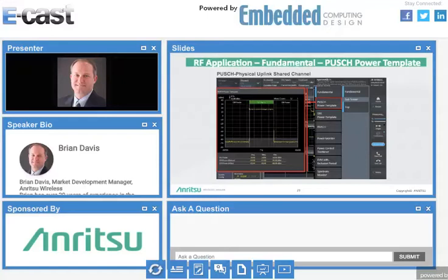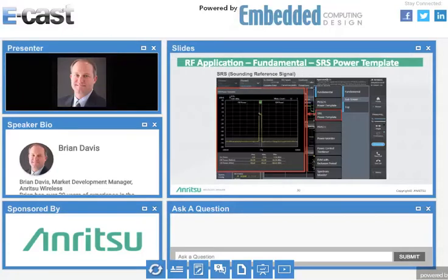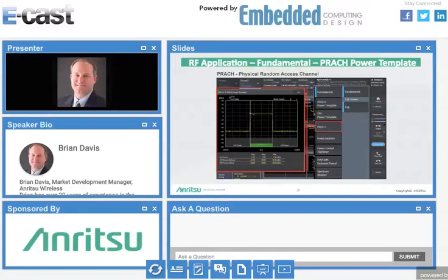Some additional measurements I thought I'd put in there too that are very helpful is physical uplink shared channel. So looking at the PUSCH information that you need to send up, because this is of course the shared information. This is, in some ways, more important than the actual data because it's the control information. The sounding reference signal, so this is always going to be measured by the base station to see how good your conditions are. So it's always going to be looking at the sounding reference signal and seeing if that's as expected, or it will be telling the UE to power up, power down.